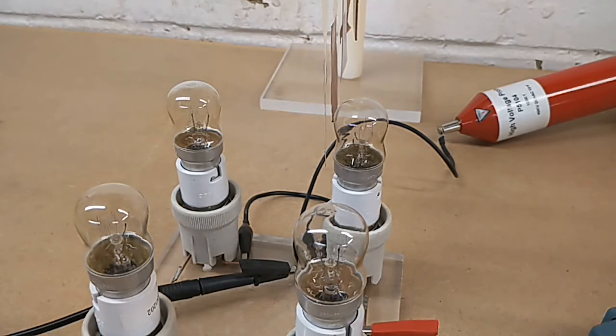And even better, of course, would be to be able to start to use impulse currents. So at the moment we're using the spark gap, we're getting a burst of energy, very much a pulse of energy every half cycle of the line frequency, which is 50 hertz, so we're getting 100, the spark gap is firing 100 times a second.